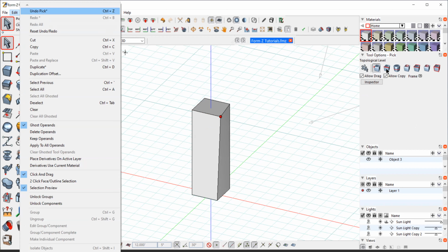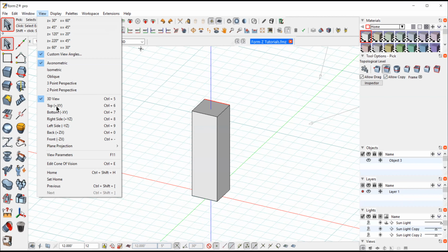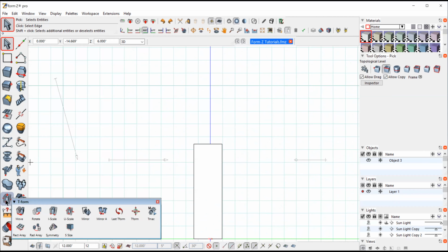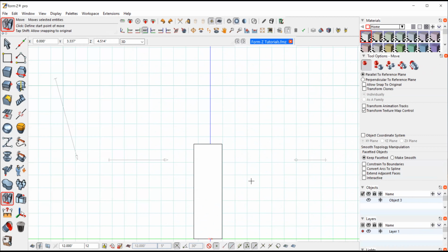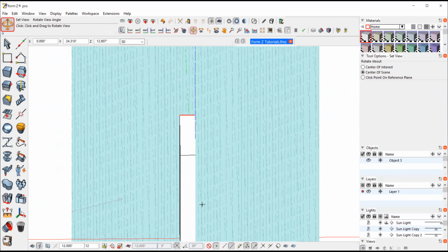You can grab the segment. You can grab a face. There's several things you can do here. So let's go with the segment tool, and I'm going to grab that back segment. I want to control how I move that. If we look at this from the right side, and we go to the move tool down at the bottom here, I'm just going to click in space and move it up. I can move it in different directions, but if I lock to the grid, I can have it go on this angle. So we can start to move these shapes around.